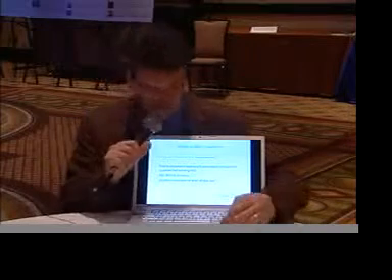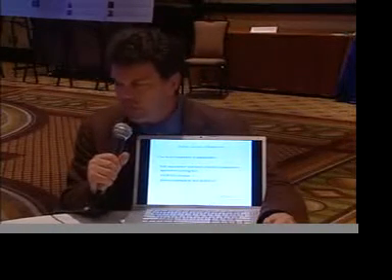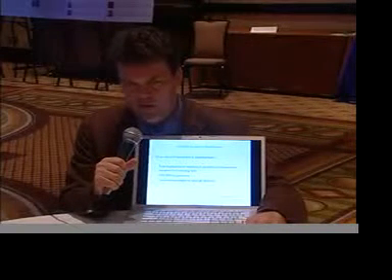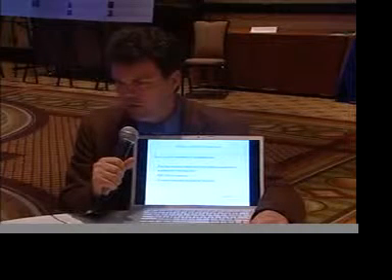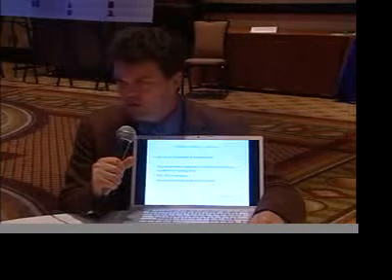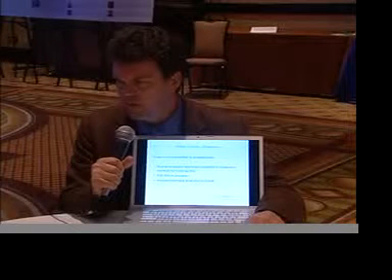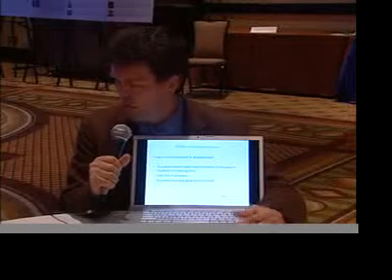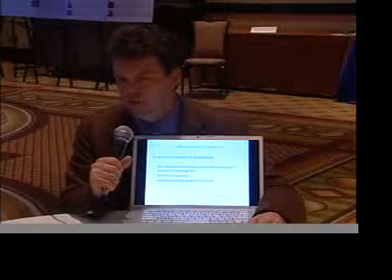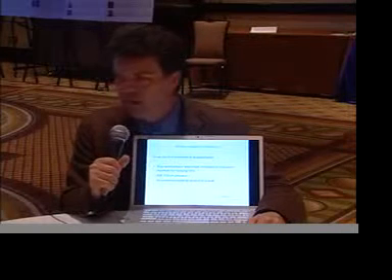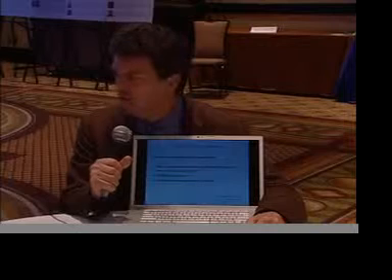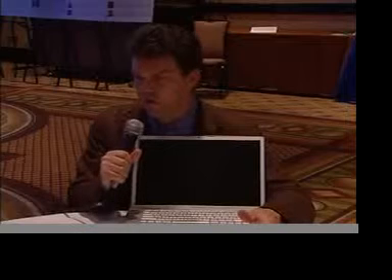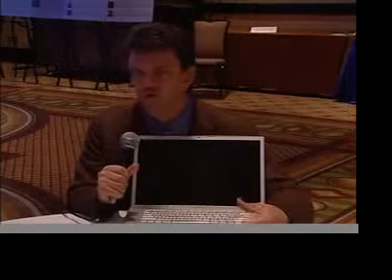The question was what the website for that is. The methodology that we use is the National Recycled Water Guidelines. It comes from the National Water Initiative in Australia. I think if you just Google pages within Australia, National Recycled Water Guidelines, you'll find the link. It's about a 400-page document. It's quite daunting, and it won't give you too many tables saying, you need this level of E. coli in your treated water. What it does is establish this methodology for working this out.